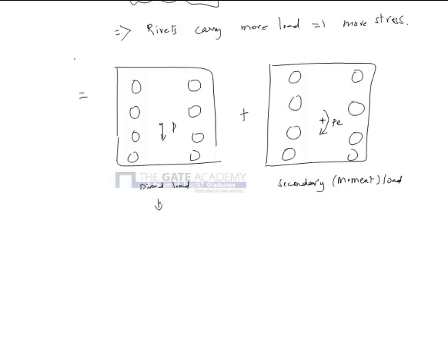So this will produce equal shear load, basically. It will be P by 8 this way. The effect of this load P on each of the rivets will be P by 8, and the effect of this moment would be producing perpendicular forces.